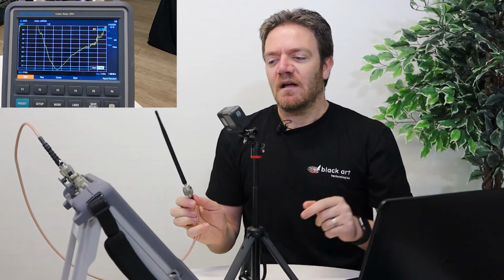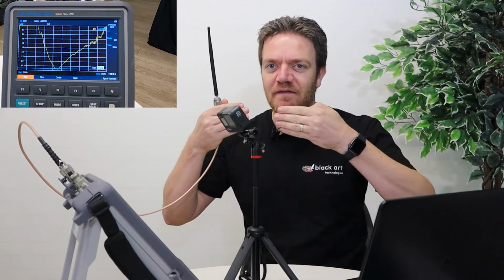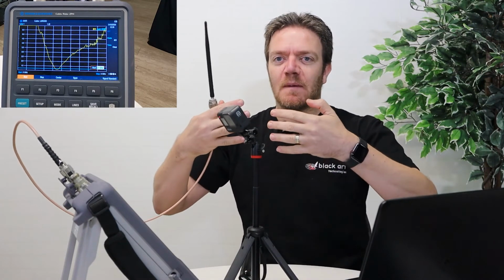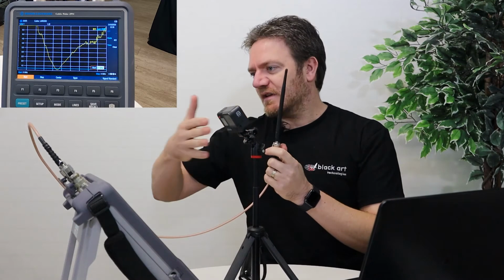In other words, at this point here that you see, there's almost no VSWR, there's no standing wave. If you think about this wave again, there's a wave coming in, it hits a wall, comes back, and the standing wave is quite high because the ratio between the minimum and the maximum is huge. This area is like there is no wall. So the wave comes and it just keeps going.